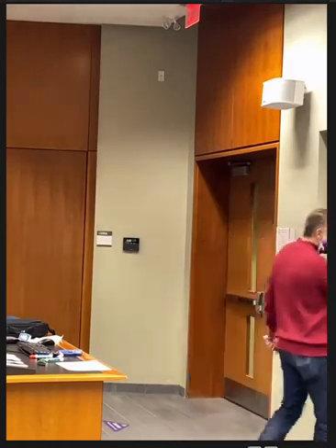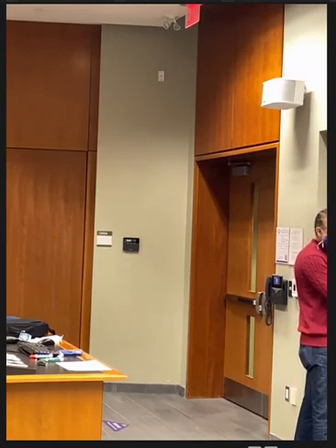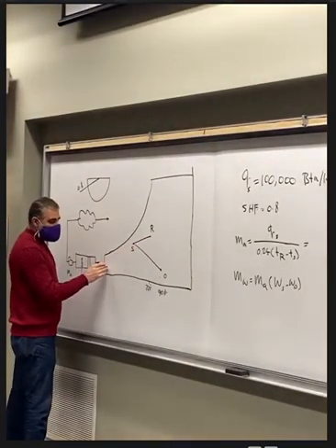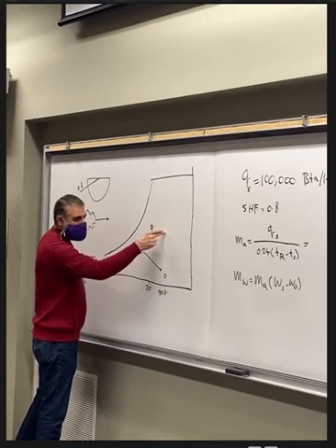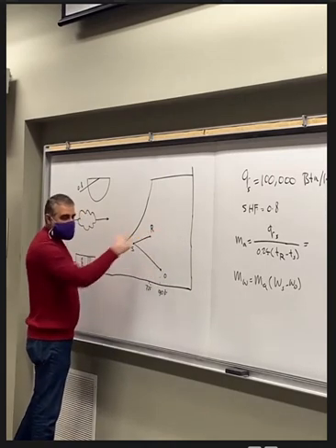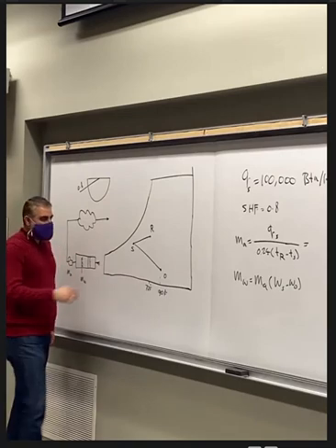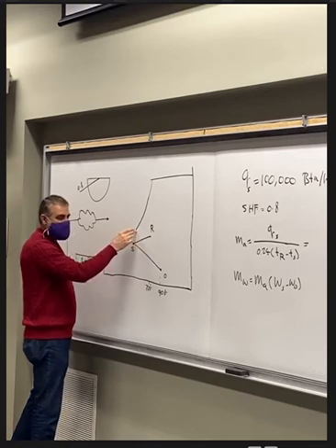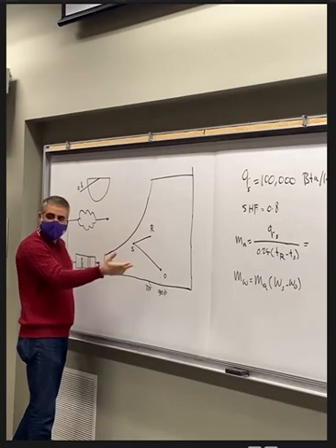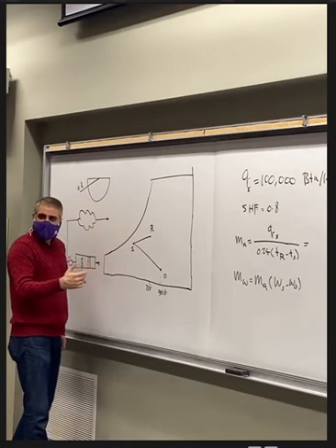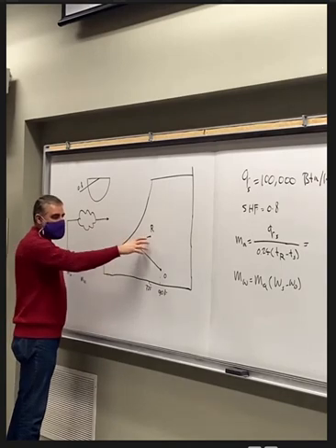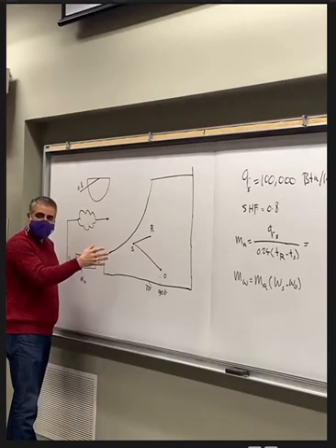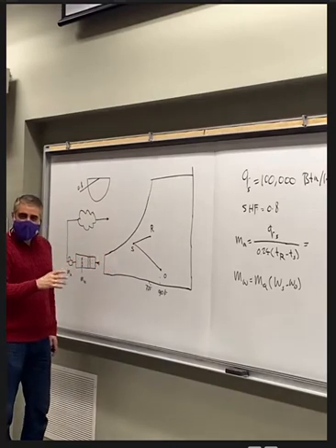For example, if the outside air was here in winter conditions, we need to reach room temperature. So in order to reach the room temperature, we have to heat the air, maybe humidify it, and supply it to the space, because we need to supply the air at higher temperature to the space. For example, this is one solution. If the outside air was somewhere in this location where the humidity is very high, in this case, you may need to dehumidify and then supply the air and heat it. So that's why the location of point O in the chart, the relative location of the inside conditions and the outside conditions in the chart, will help you to find out what is the proper air handling unit that can be chosen for this question.